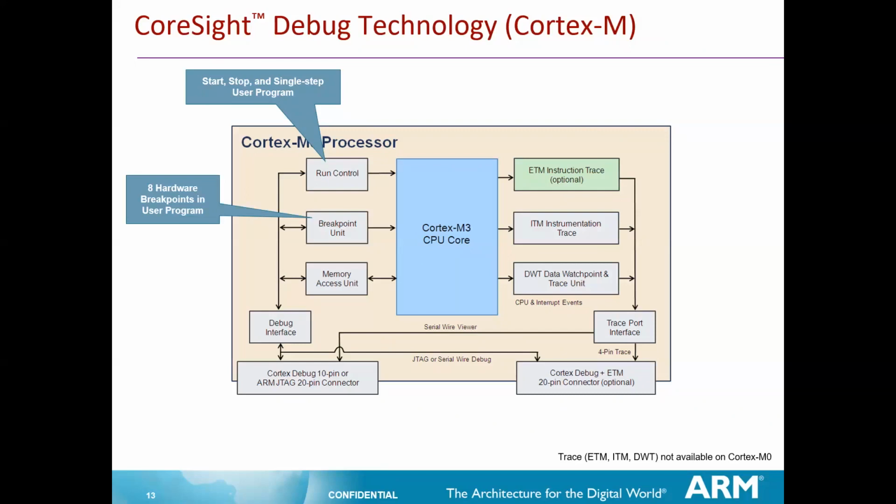So in the main hardware, I hope the team is aware what is a software breakpoint and a hardware breakpoint. To quickly tell, a hardware breakpoint is the one when you're setting the breakpoint in the flash. When you're loading the code to the flash and you're executing the code from the flash, the breakpoints you set are hardware breakpoints. Any breakpoint you set in the RAM is called a software breakpoint. RAM usually has more memory, so you can set an unlimited number of breakpoints there.